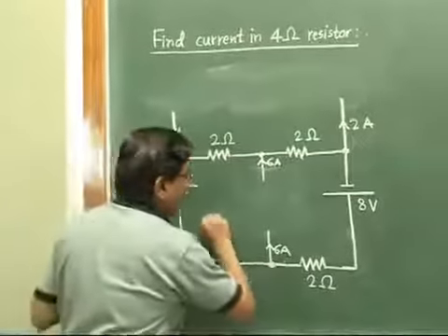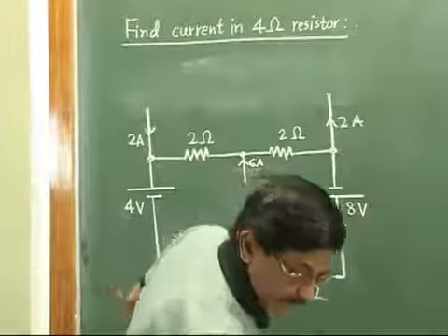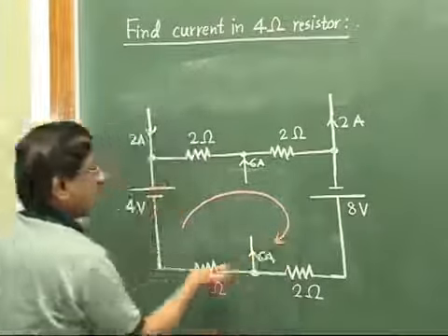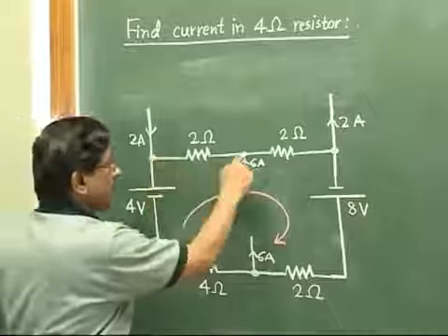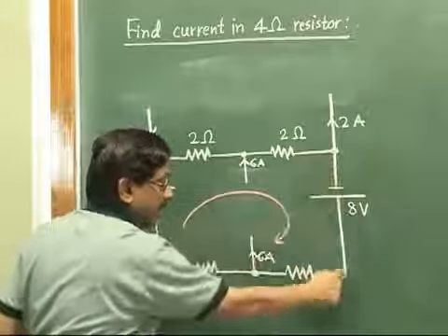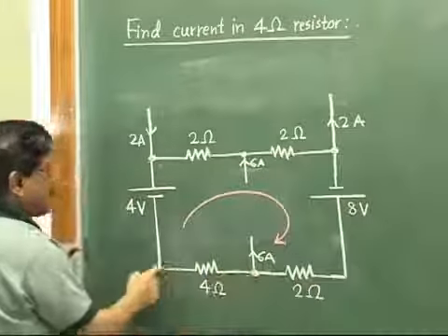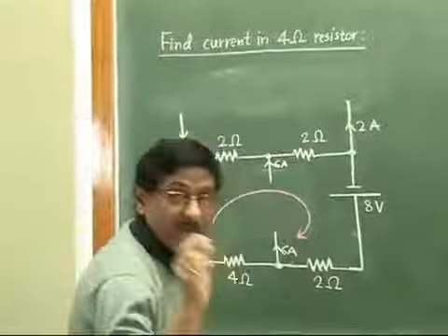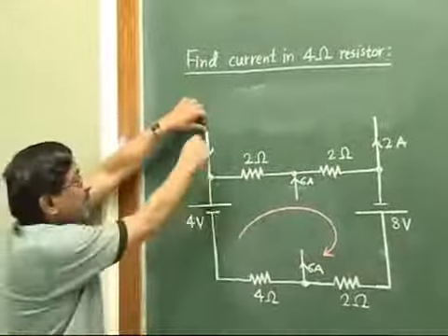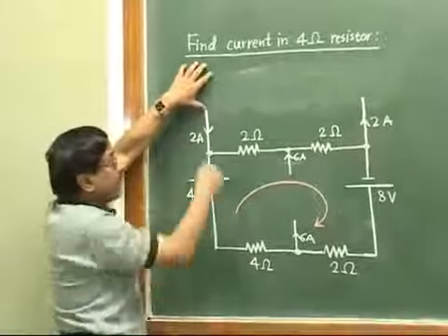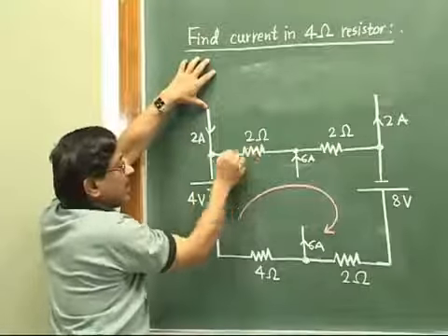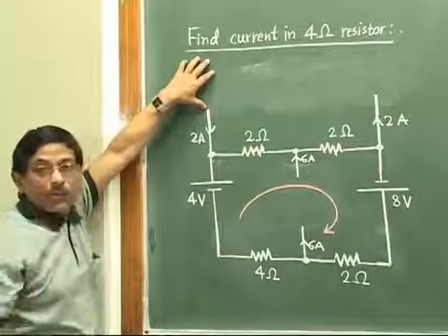Okay, we now identify the loop like this. Our loop is like this. From this point here, then here, down, left, and again to the original point. And now see how to distribute the currents. See 2 ampere, suppose we start from this end. 2 ampere is coming to this node. However, there will be two paths, means we need to take one variable.